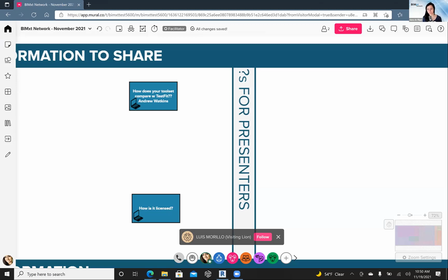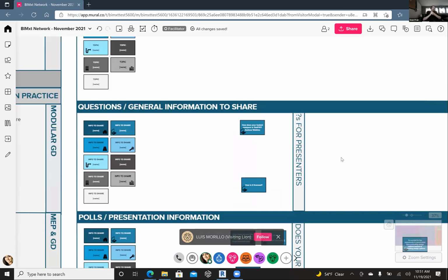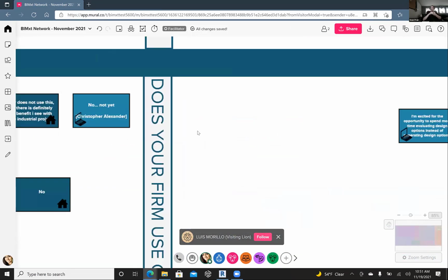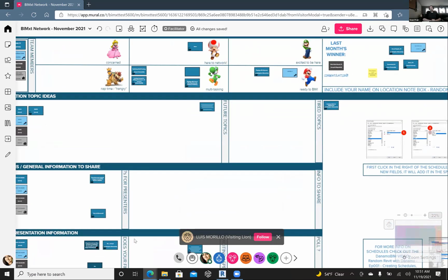Zach is asking, is constructability review part of that feedback loop? And later he said with insulation. The feedback loop, the whole idea of all of it together, is what I think a lot of people are working on and what excites me. But we're not quite there yet. And one of the things that's missing on the HVAC thing is there's no look at how much the shaft costs, right? And that's a huge factor. Also, there's no fireproofing in there actually. If you have ducts, you need fire dampers at certain things, and that's not included in it. So even more design knowledge would need to be added.